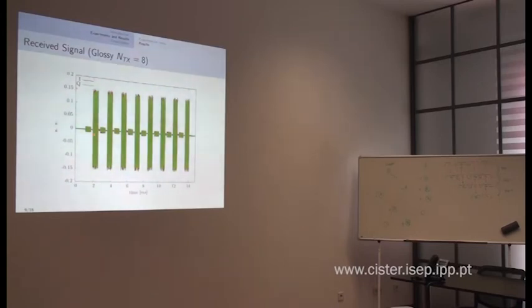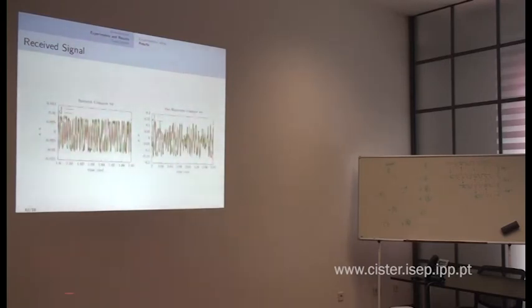And then this in here is when two nodes are transmitting concurrently. And it's right here where we want to pay attention. So the reason this is attenuated is because, as you can see, if we look at the signal, this will be the initiator. You look at the complex baseband signal, and because the information is in the phase, the amplitude is more or less the same. The magnitude does not change. It's not that the amplitude is being modulated, what is modulated is the phase.